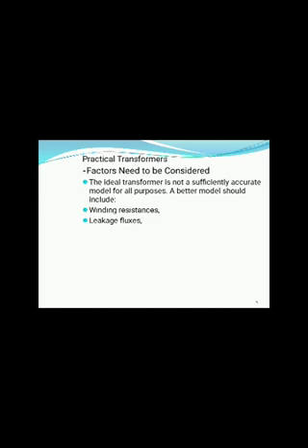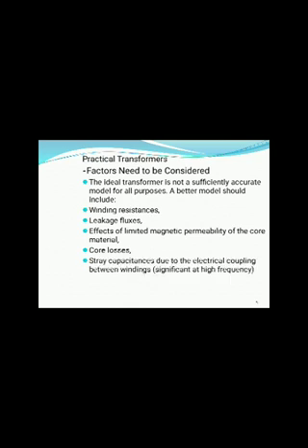And also another one is leakage fluxes. Another one is the effect of limited magnetic permeability of the core material and also core losses, and stray capacitance due to the electrical coupling between windings. That means it is significant at high frequency.